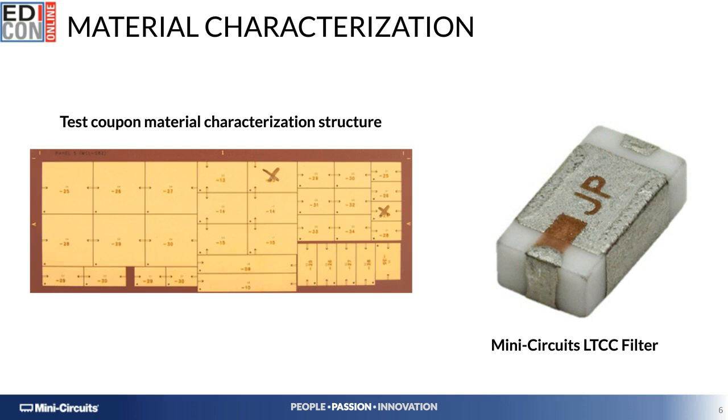To measure the dispersive and anisotropic nature of the dielectric constant and loss tangent of several different material systems, as well as the conductivity of different pastes, this test coupon was actually fabricated. We use probing as a method to test the same, and a homebrew algorithm to capture the actual measurement data on the parameters of interest, mainly dielectric constant and loss tangent.